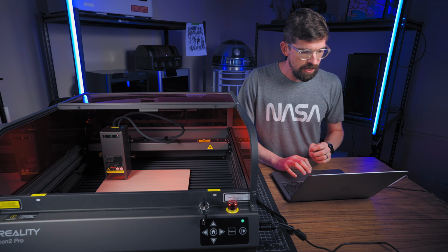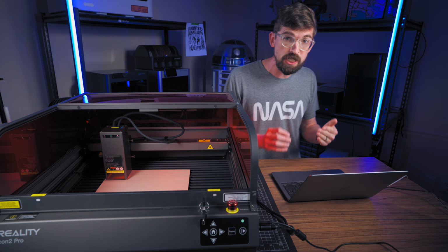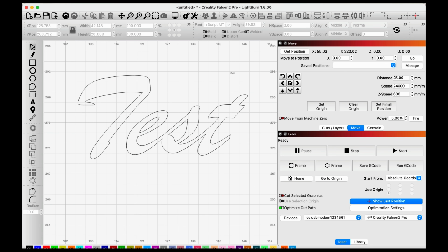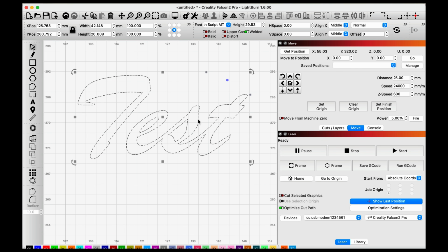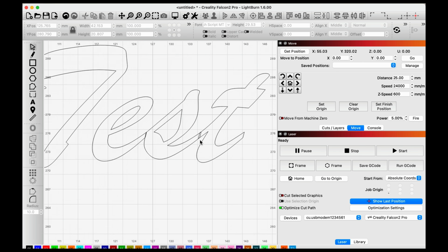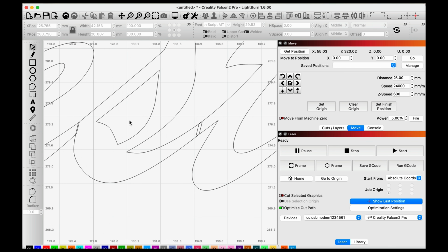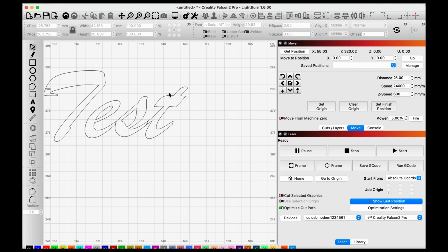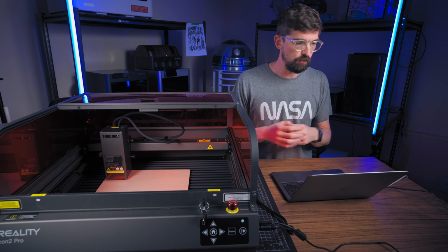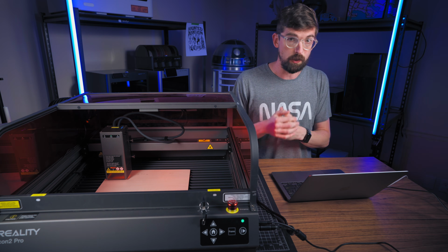Not only will that make your engraves faster, but especially if you're cutting that out, it's going to follow the lines. So if this wasn't welded together, you would actually have some lines right here that are cut. For whatever reason, if that setting is turned off, make sure you've got that turned on so that everything is welded together so they come out as one piece, because that's probably the way that you want it.